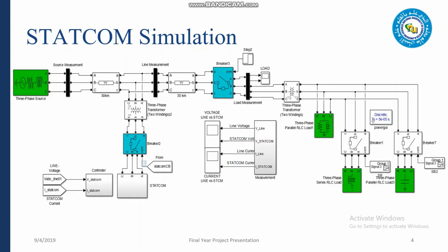To induce transient effects that create voltage fluctuation, we use a 10 MVA inductive load switched in for 0.1 seconds from 0.45 to 0.55 seconds of our simulation, which induces an undervoltage condition. And for overvoltage, we connect a 10 MVA capacitive load switched in for 1 second.